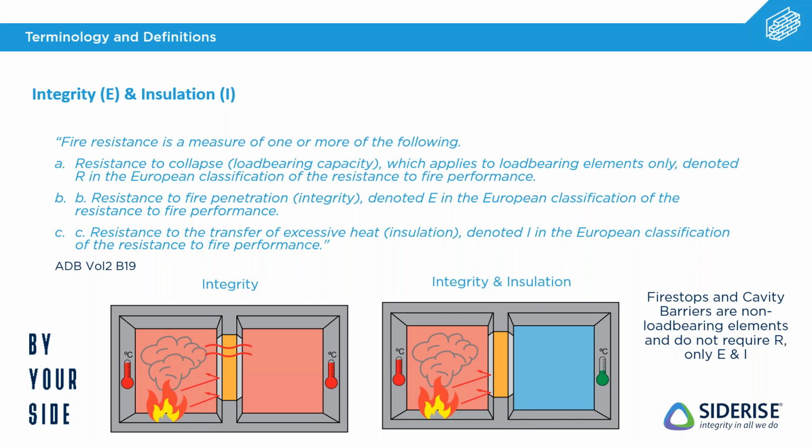The only thing you're missing is heat. So if that fire is able to not necessarily get through the barrier, but the heat of it is able to transfer through, then you can get spontaneous combustion on the non-fire side. So it's important that when we're testing cavity barriers, we're not just preventing the fire, the actual flame getting through, and also the smoke, but also we need to make sure that not enough heat is getting through it to start a fire. And that's what the insulation in terms of testing cavity barriers is referring to.